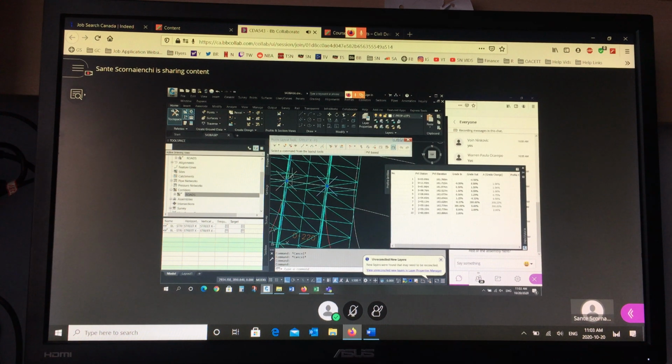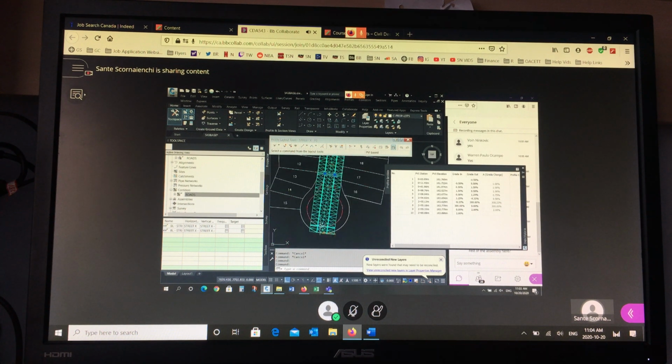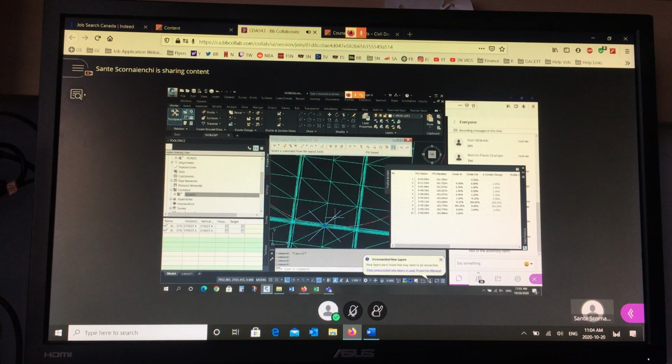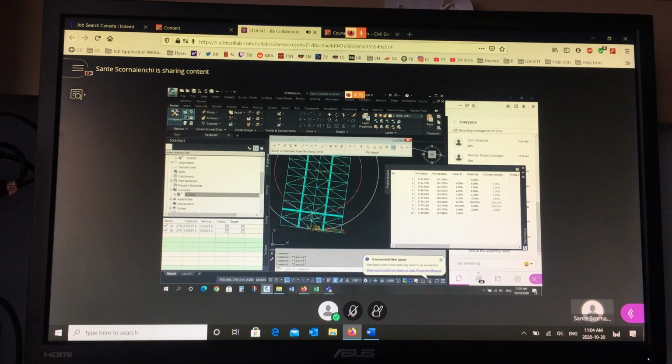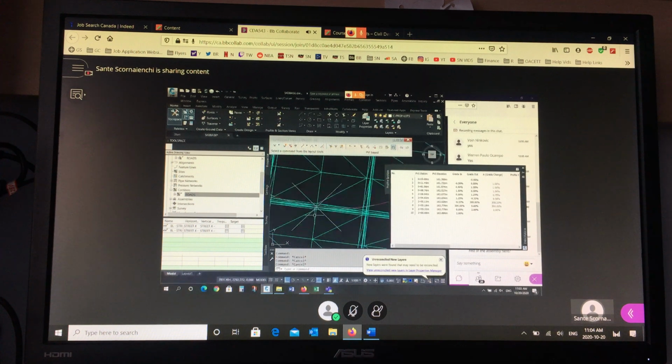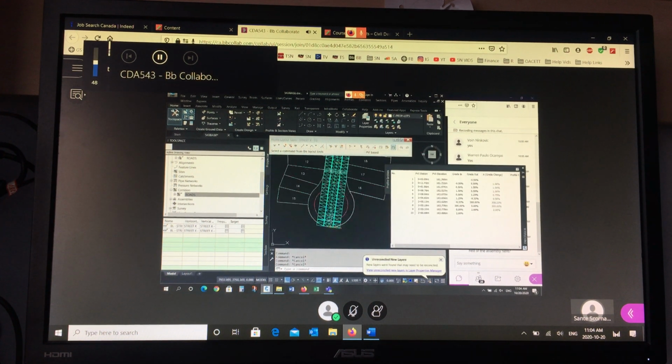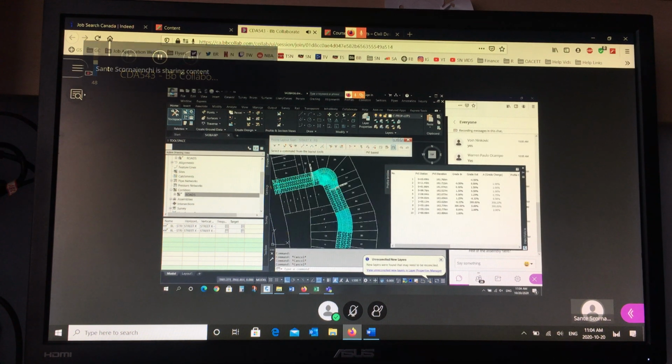That's where I match, right? So my profile design, station and elevation here and here is correct. And as I come around, the station and elevation of the gutter is correct here as well. So those are the 3 points that define the profile of the gutter. If you missed that from last day, here we have 3 points. Last week when we were looking at the crescent, we only had 2 points.